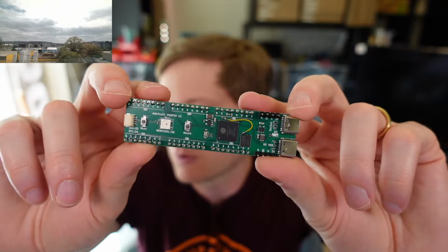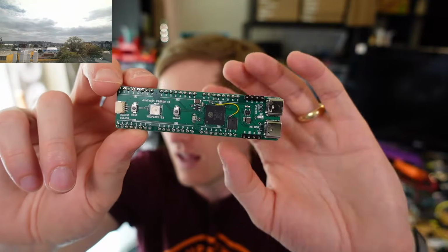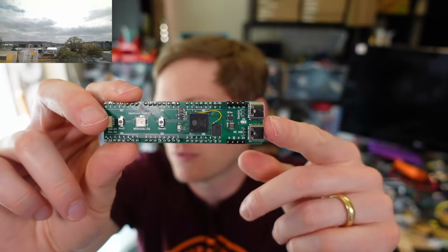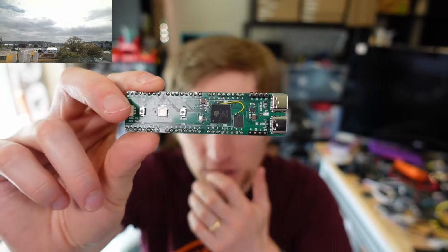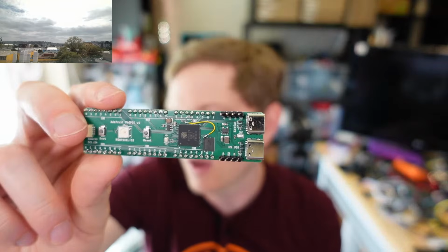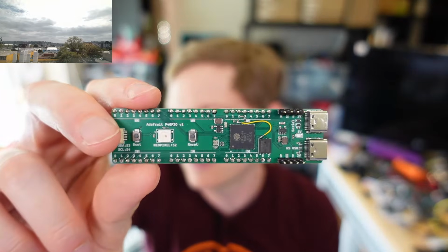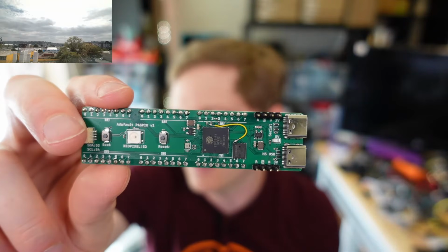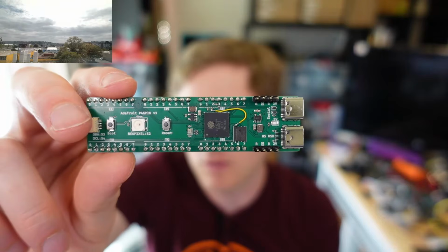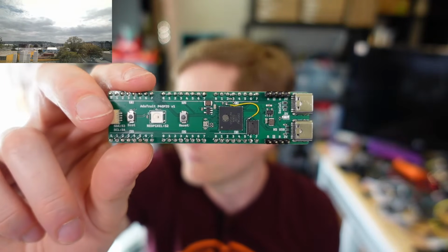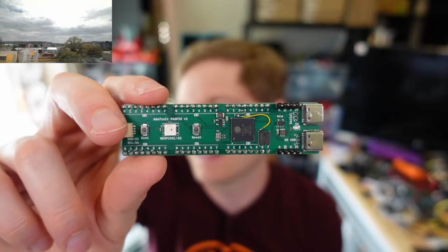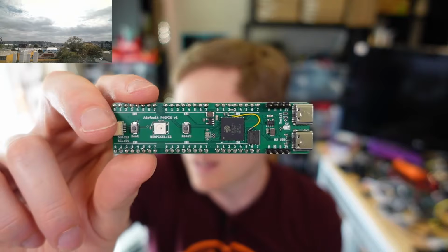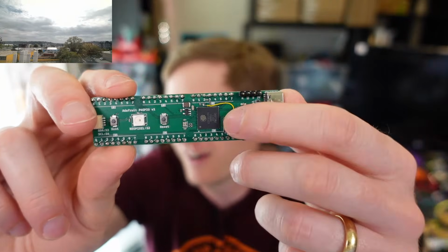When I first got these boards, I didn't have the headers on, like I said, and I plugged them in, and I was able to talk over both of these USBs to the ESP32-P4. However, I wasn't able to load code. When I would do a flash command, it would look like it flashed, and then it would do an MD5 sum or some sort of checksum over it and say they don't match. And when I looked at it yesterday, I realized that I had forgotten to connect to the power.